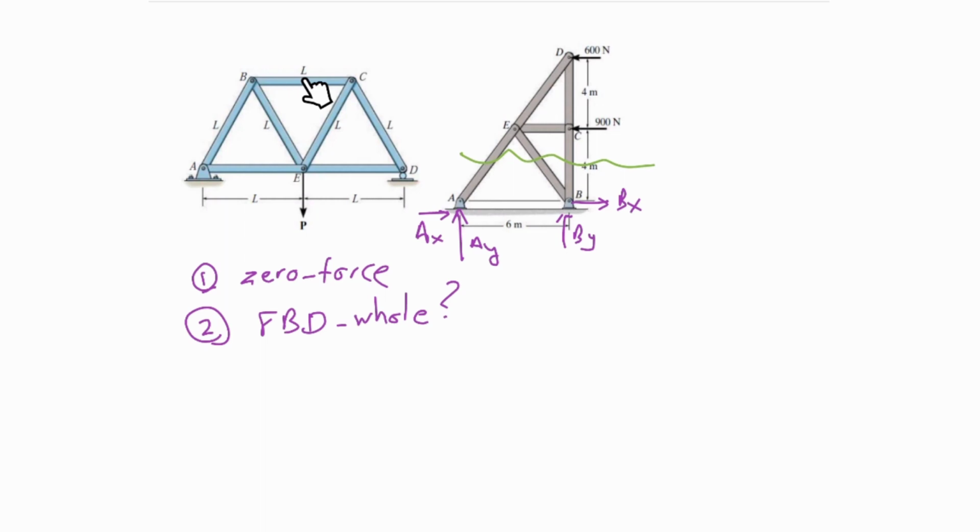However, in an example like this, you cannot go through that without finding the reaction forces, meaning that here you can do the cut, you can find three links and three unknowns and write down the equation for this part, do the free body diagram of the system for this part, and then write down the equations, find unknowns. But here you cannot do that. Why is that?